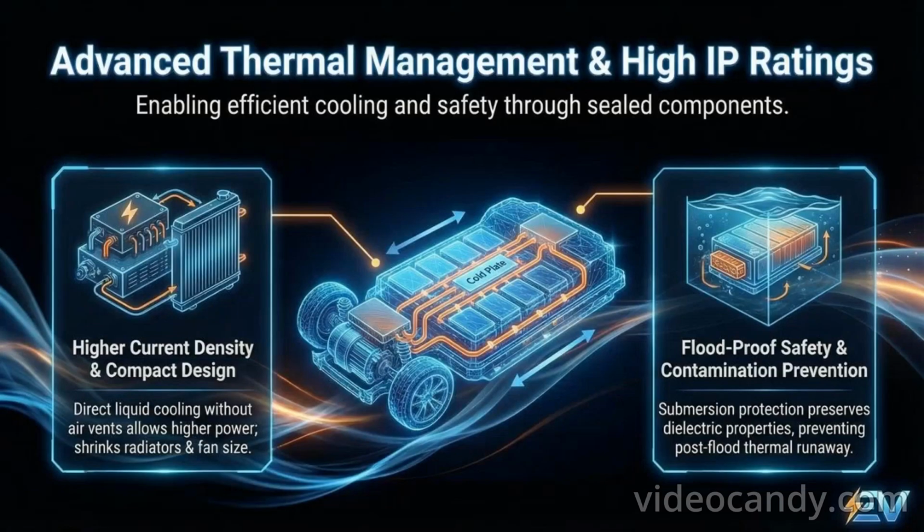High IP ratings make liquid cooling safe for EV batteries and motors. Because the housings are sealed, water sprays or road splash cannot disturb the coolant loop. That means engineers can push more current and heat through cells without adding air vents or big fans. It also protects the coolant during floods, so dirty water can't mix in and cause insulation failure or safety issues after a submersion event.